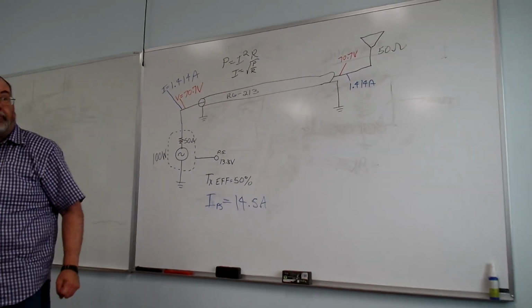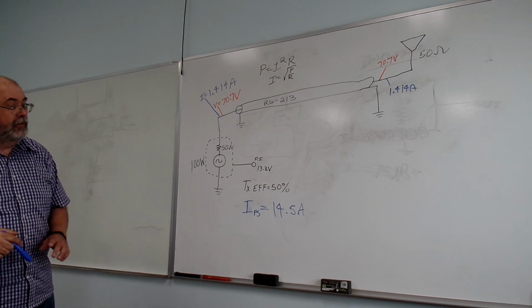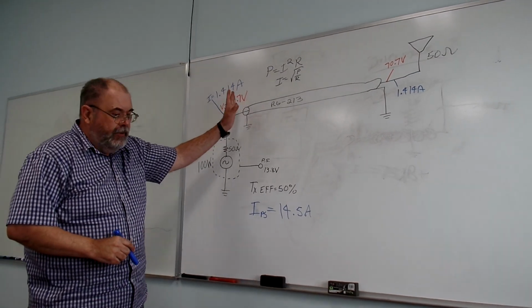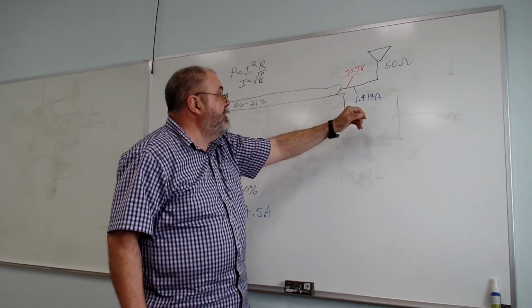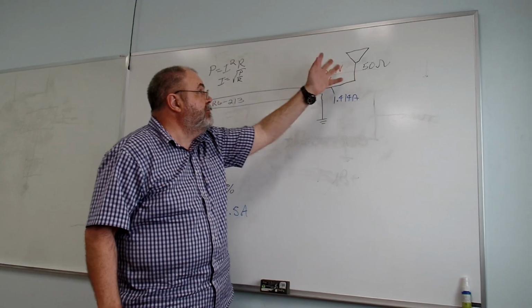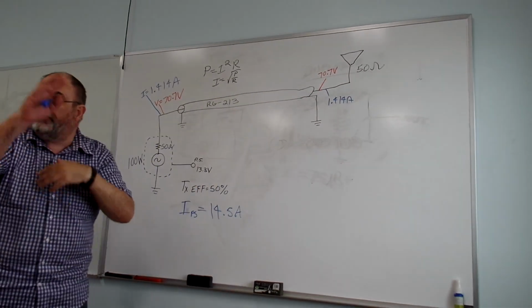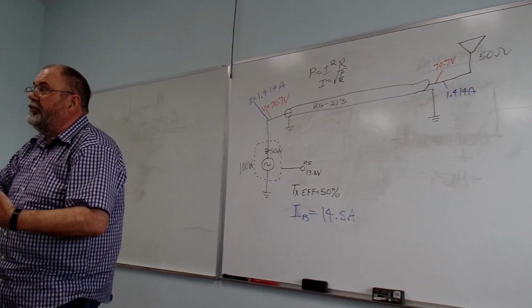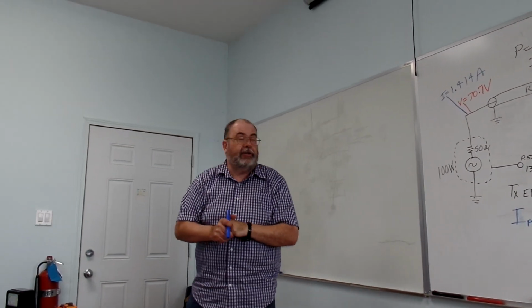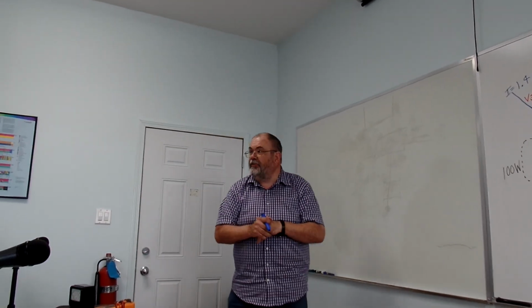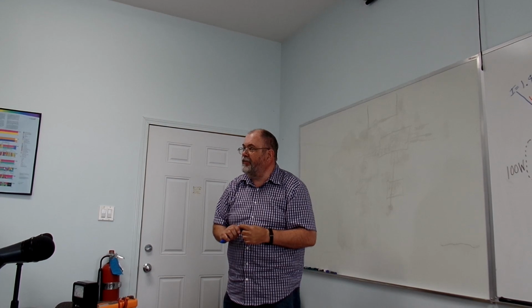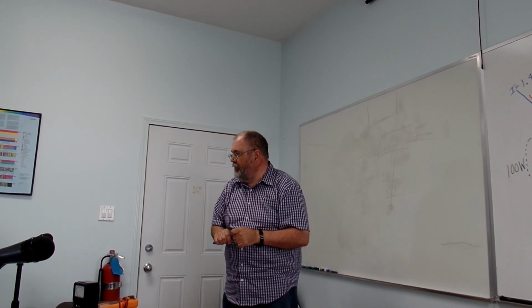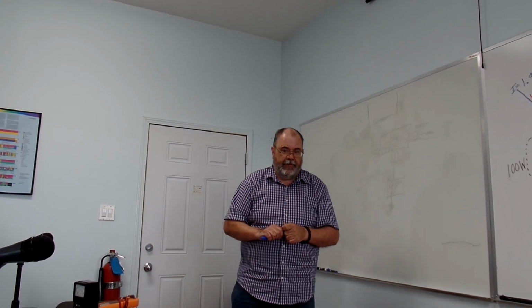does the math work out? Ignoring this now, if we got 70.7 volts and 1.41 amps and 50 ohms, do the numbers go around in the circle? It all comes out to 100 watts. So we're going to radiate that 100 watts out into the ether, and people are going to hear us for miles around. We hope. You ready? Okay.